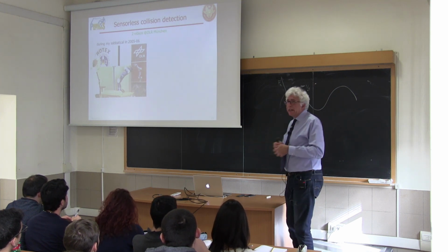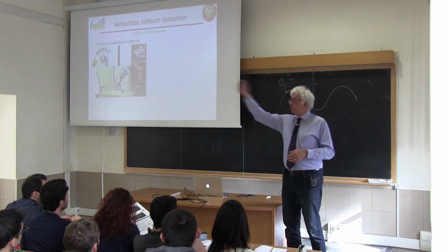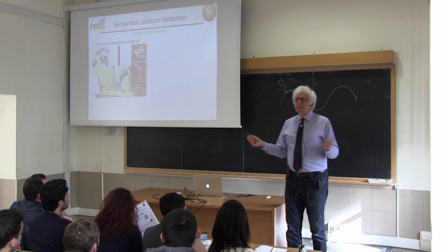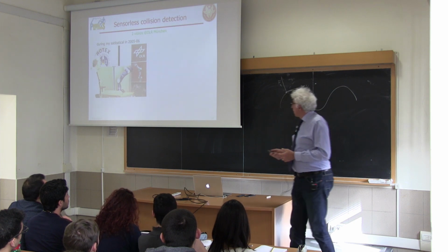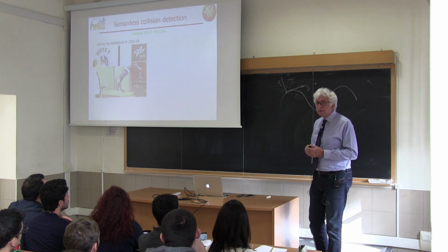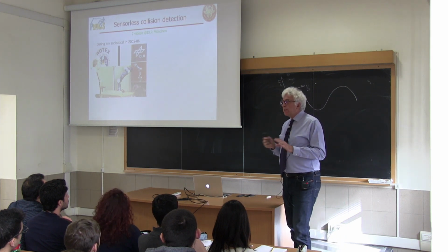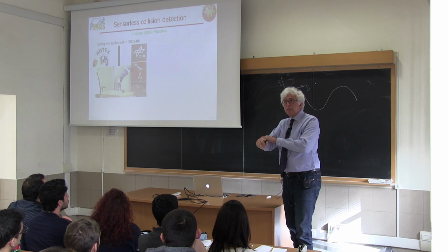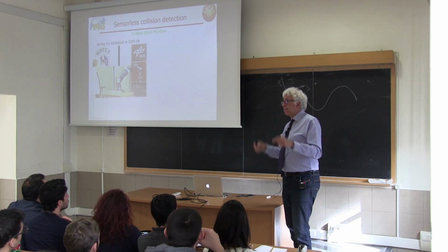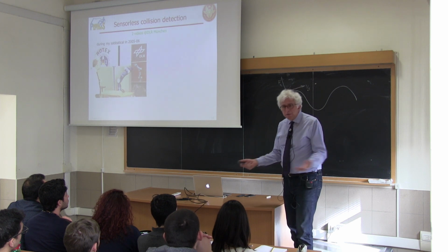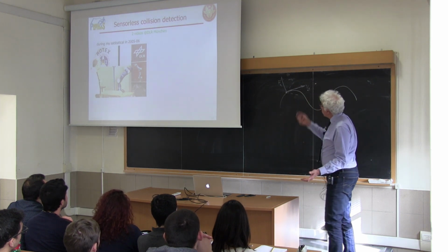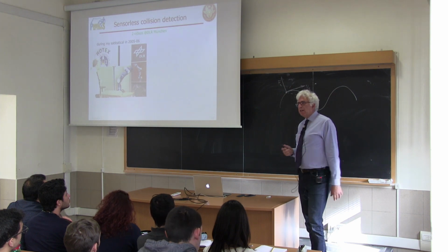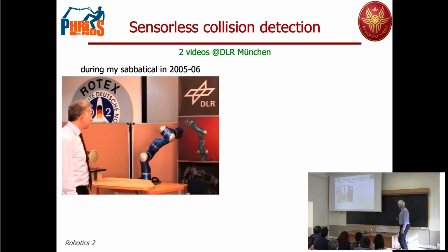And the robot is commanded here to make some free motion, go from an initial position to a final position and then back and forth. And it would do so if it doesn't hit anything. But in fact, it will hit my arm and will detect this collision without the need of any exteroceptive sensor. So in this video, there's no camera, there's no sensitive skin, no proximity sensor, nothing else than internal encoders, the minimum sensory equipment. So the reason why I'm saying sensorless is not completely without sensor, but with no special sensor for this contact detection. And this is what happens.